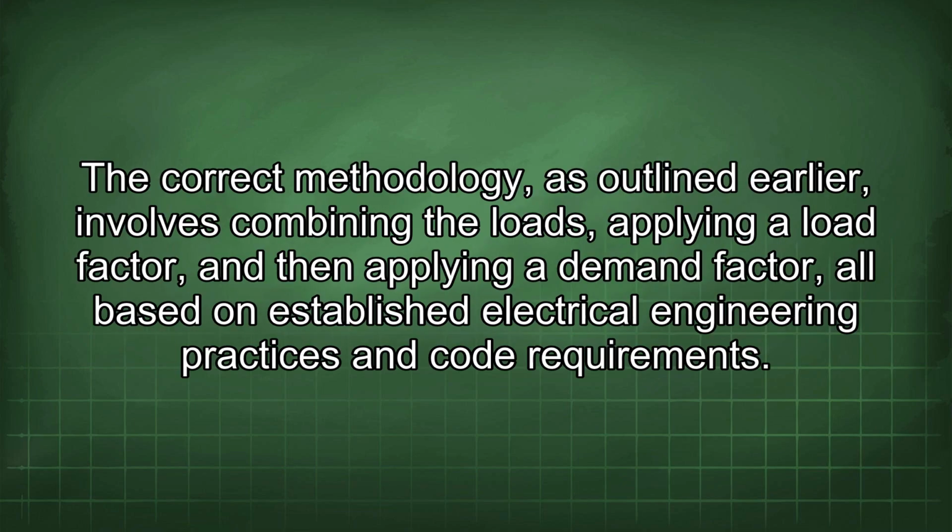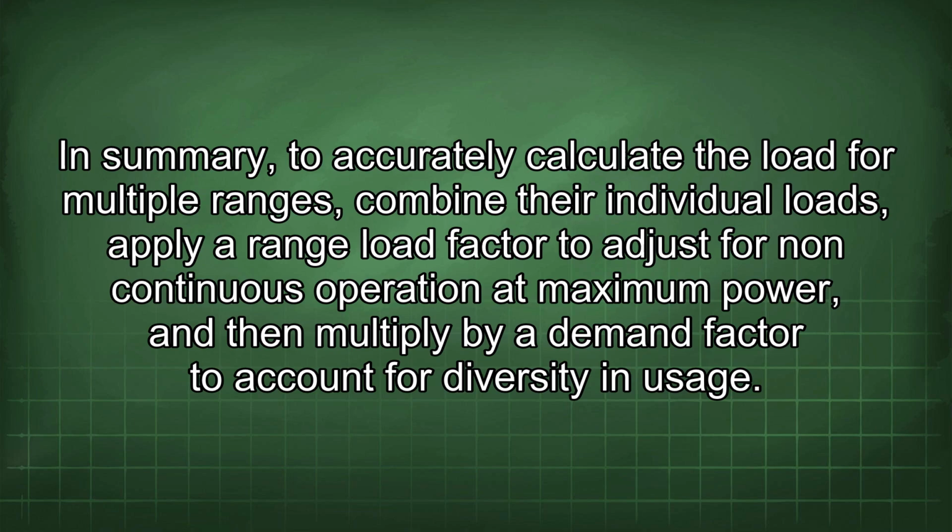The correct methodology, as outlined earlier, involves combining the loads, applying a load factor, and then applying a demand factor, all based on established electrical engineering practices and code requirements. In summary, to accurately calculate the load for multiple ranges, combine their individual loads, apply a range load factor to adjust for non-continuous operation at maximum power, and then multiply by a demand factor to account for diversity in usage.